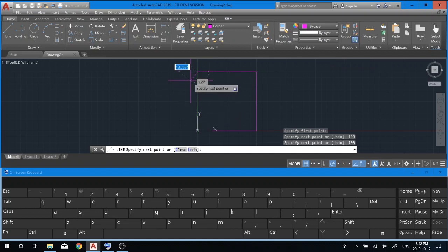Lastly, we got options now. I can snap it in, give it a direction, type 100, or I can simply click on the end point of my first line. All right, I'm done drawing my line, 100 by 100, so I will hit spacebar to end, and now we're going to go ahead and save our border.